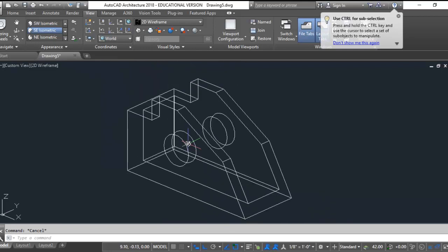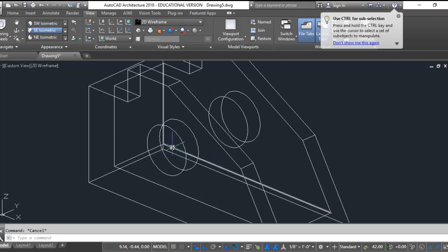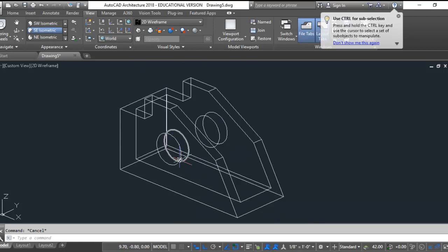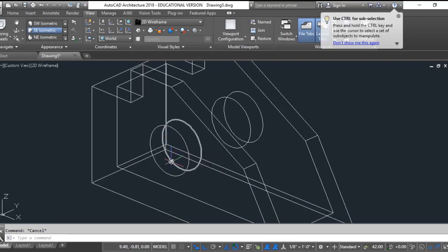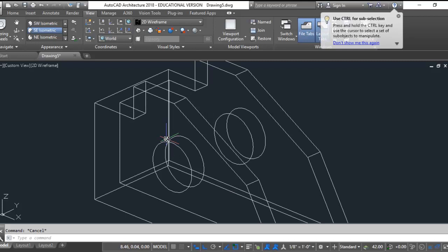So I'm going to start on the hardest face, which is the face that we're staring at right here. And to do that, if you look here, I have 1, 2, 3, 4, 5, 6. I count right, 1, 2, 3, 4, 5, 6, actually 7. I have 7 faces here that I need to somehow get shaded. And it's real difficult because these 3D shading commands only work up to a 4-sided figure, and rule surf only works with 2 sides, so we've got to think about how we want to divvy this up. And I think what I'm going to do is cut up this circle into 7 pieces, and then I can rule surf to each of those 7 pieces. So bear with me here.